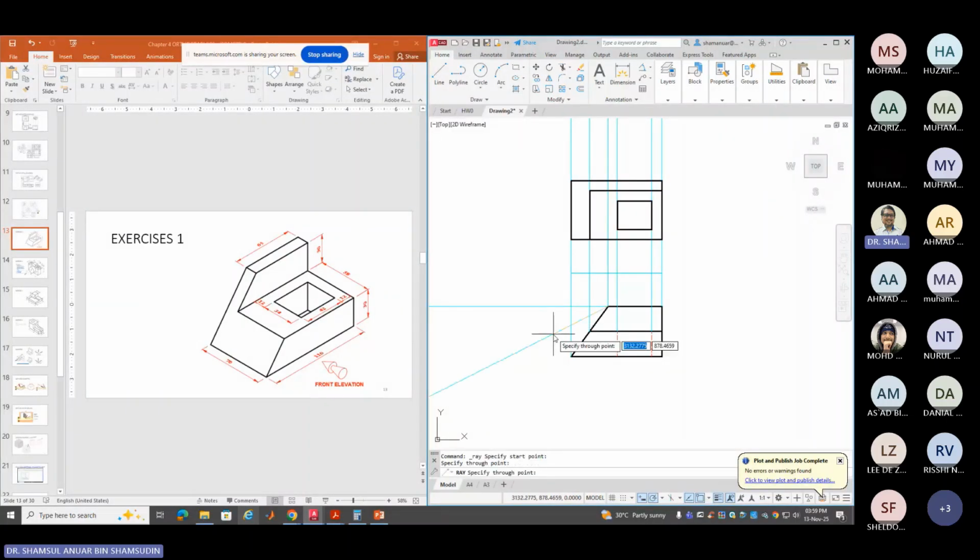So to the left, because this is front, this is left. You want to choose the side that will give you the most information, the one where you get fewer hidden lines, so that it provides the most information.